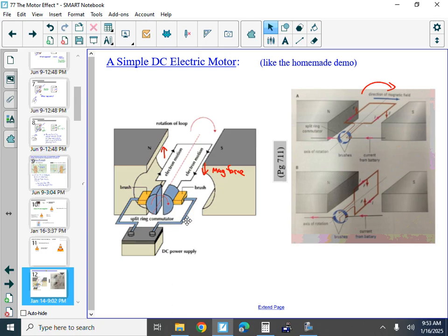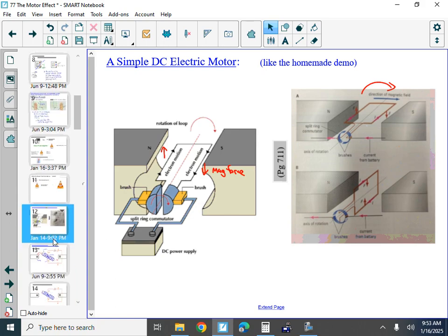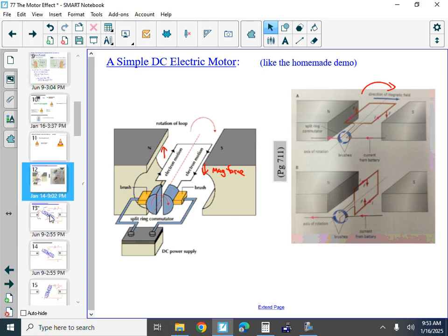So same analysis as before. If you had electrons flowing whichever way, right? So analyze the left side here, electrons flowing into the page. Magnetic north is from left to right. With my palm, I wish I had a webcam going, I could show you my hand live here. But yeah, force will be up. The other side, it reverses, so it's down, and so you can get this rotation. And so that's the diagram of how this thing works.